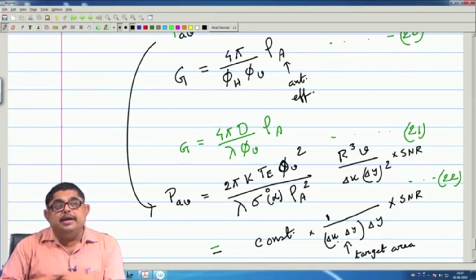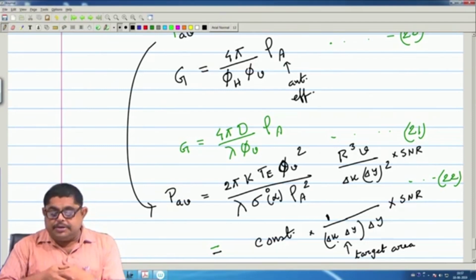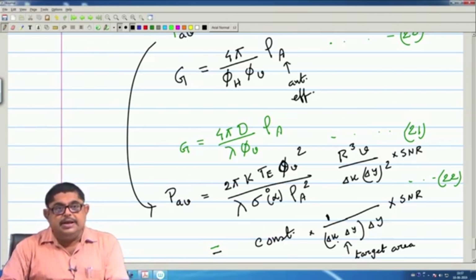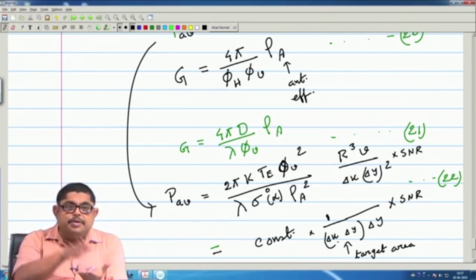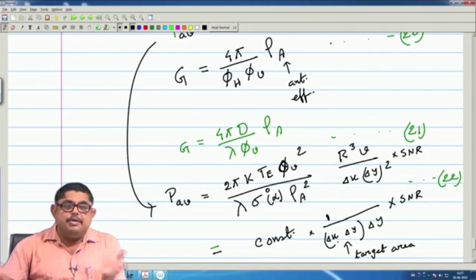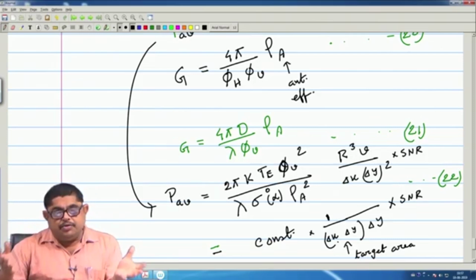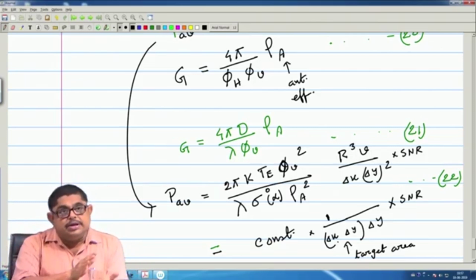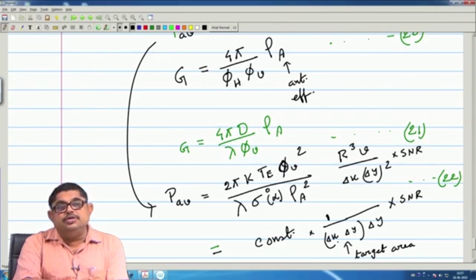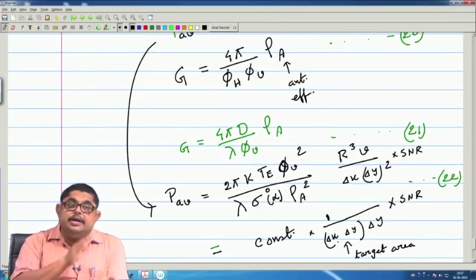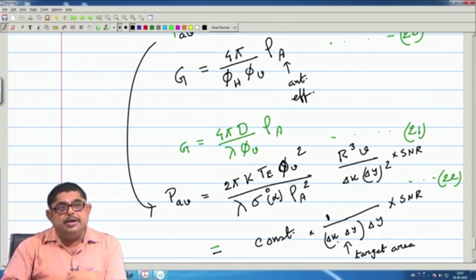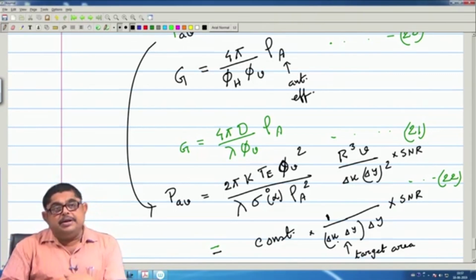One thing is remaining: the structure of a SAR processor, the architecture of a SAR processor, which I will do in the next class. So, what we have seen is how, from the basic movement of the SAR, you can find out the phase history, you can find out the cross range resolution expression, and then what the limit on that resolution is. That turns out to be half of the real aperture length.